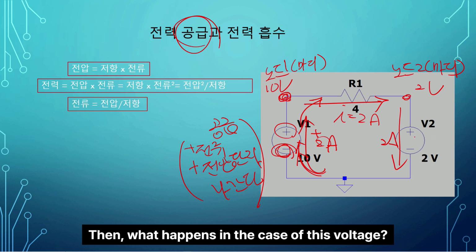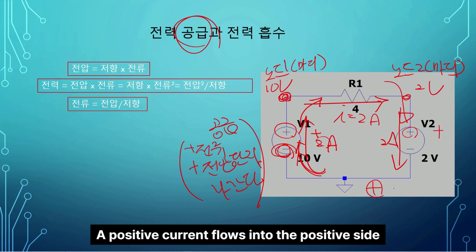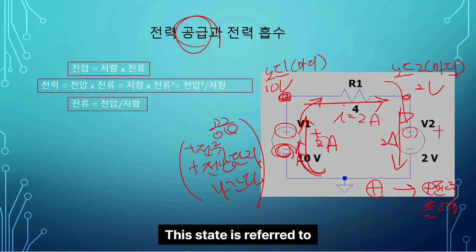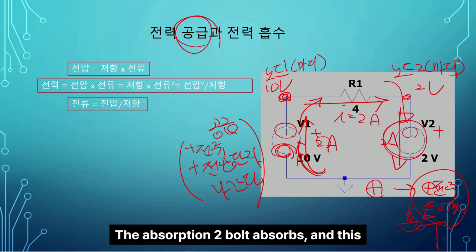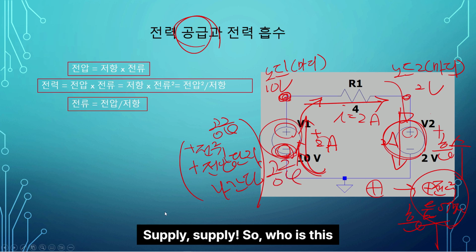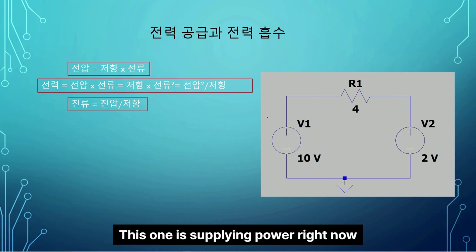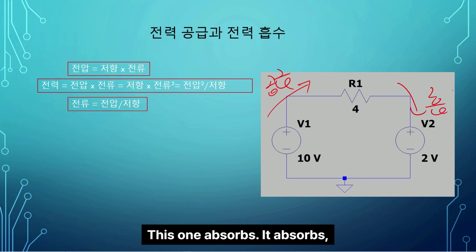Then, what happens in the case of this voltage? Here, a 2 ampere current flows into the positive side. A positive current flows into the positive side. This state is referred to as absorption. The 2 volt source absorbs, and the 10 volt source supplies power. So this one is supplying power right now. This one absorbs.